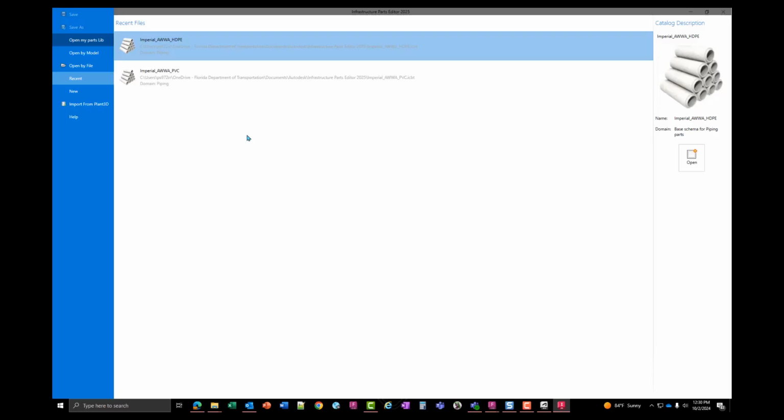And the video that Justin, that we're about to play, is going to go through the process of creating subparts. We'll just call it drainage part subassemblies. So you're going to create subassemblies in Inventor Pro. Subassembly meaning bottom round sections, tops, grates, each one of those are subparts. And you use Parts Editor to assemble those subparts into one part.